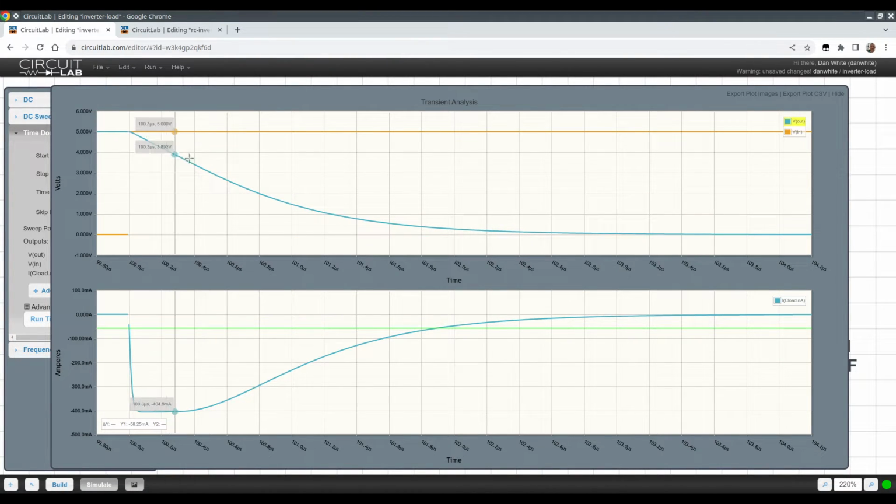We notice the output voltage is decreasing. Well, there's negative current from the capacitor. That means current is going out of the capacitor, or discharging it. In this region from 100 microseconds to 100.4 microseconds, looking on the bottom, the drain current is constant. And you can see that the drop from here down to here, from gate voltage to drain voltage, is about the threshold voltage, 1.8 volts or something, I think the threshold was in this model. And we switch from saturation mode to triode mode.